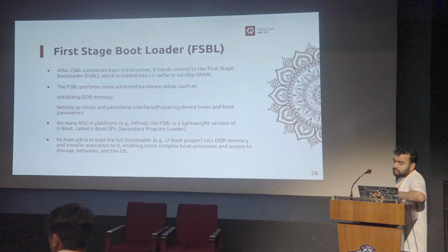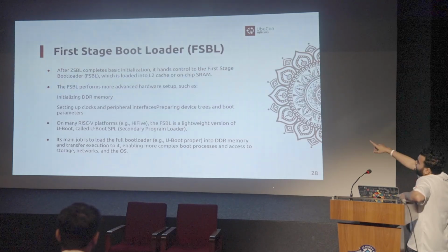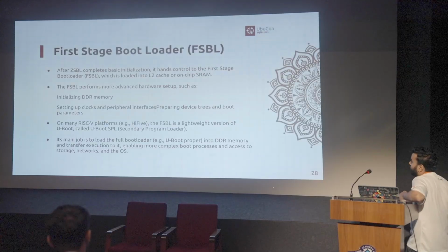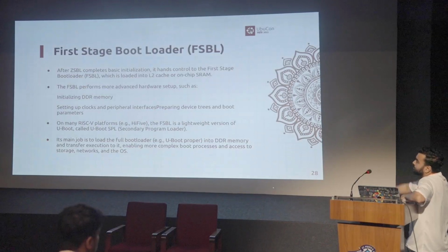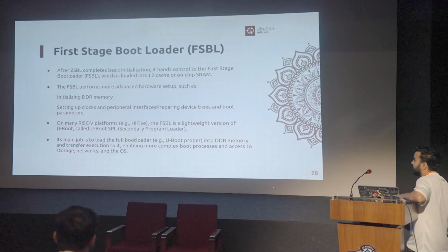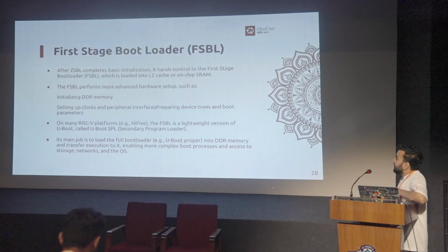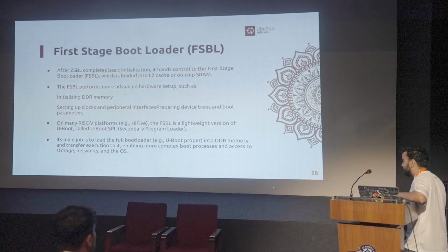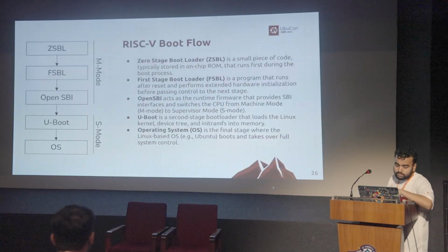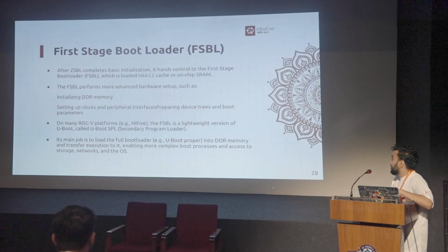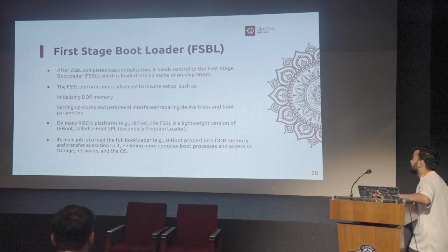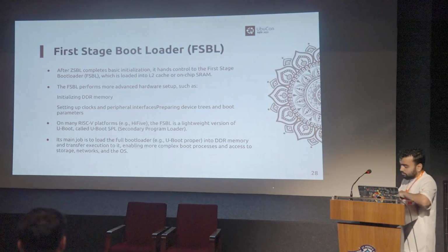Here it works with the L2 cache or on-chip SRAM. The first stage bootloader works on that. It is responsible for initializing the DDR memory. It sets up clock, peripheral interfaces, device trees, and boot parameters. Its main job is to load the full bootloader, the one we have just seen over here.